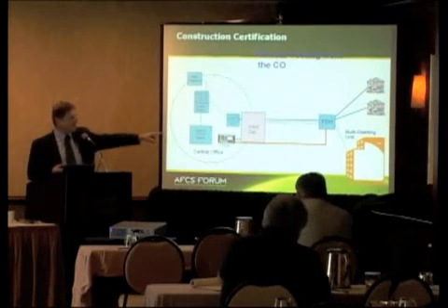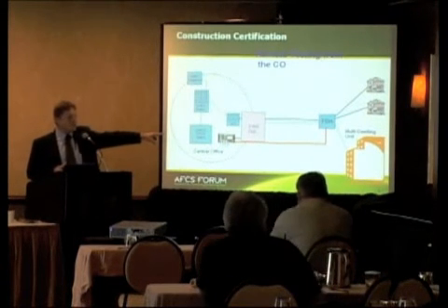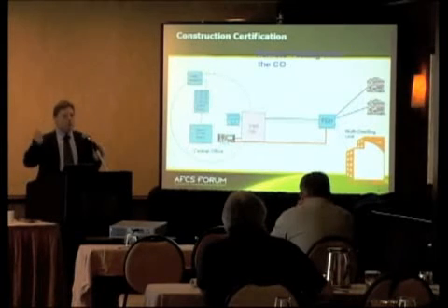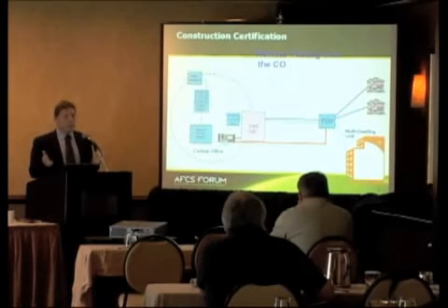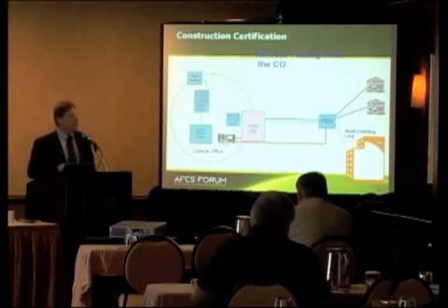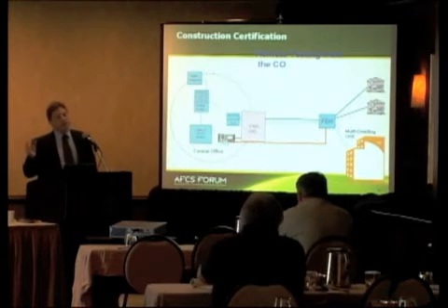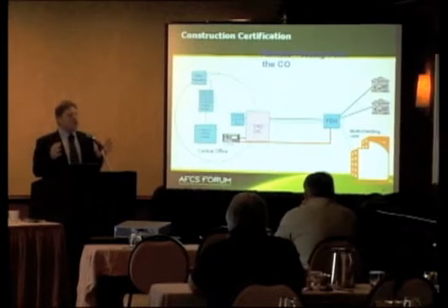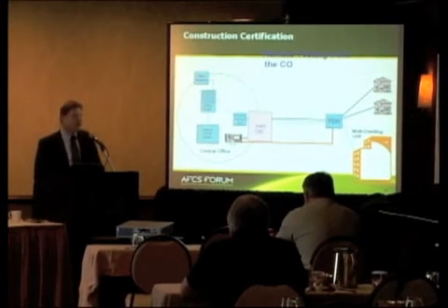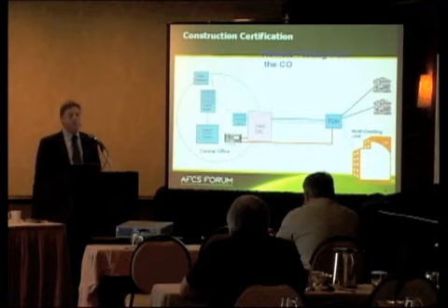remotely by having a single OTDR in the central office with a fiber line, and it be manually connected to each F2 one at a time, in which case we do have personnel involved, or we have a portable test set, or optical switch, that would be placed in there to run through the testing. Ultimately, rather than a portable one, we'd want a permanently installed one.